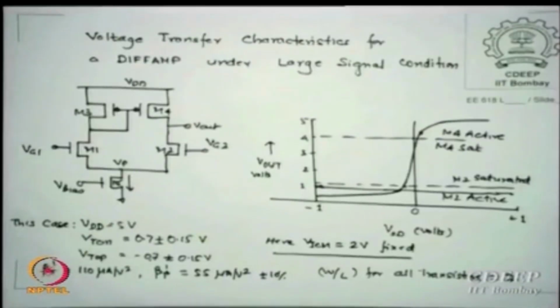We want to see the limits. So these are called limits or ranges. Two ranges of interest to me: one is at the input, the other is at the output. The output voltage maximum to minimum that I can get is called the output swing. So one of the specs of a difference amplifier, or for that matter an op amp, is the output swing, how much output maximum you can achieve from a given circuit which you design. The other of course is how much maximum to minimum input I can vary which will still give me gain, is that correct? So what does that mean? The device still remains in saturation for those inputs, beyond that they may not.